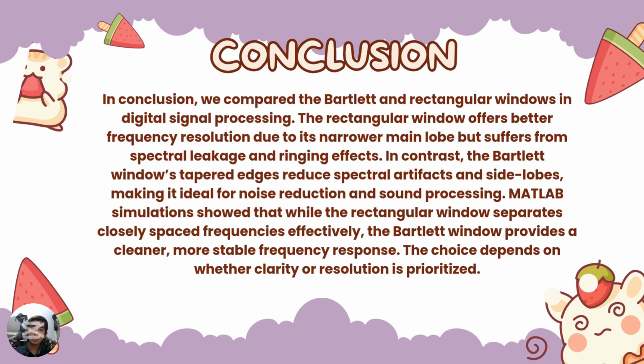The experimental results confirmed this insight. Frequency domain analysis revealed the rectangular window's propensity for the ringing effect as a consequence of the Gibbs phenomenon, while the smoother transition of the Bartlett window reduced this oscillation, delivering a more stable frequency response.